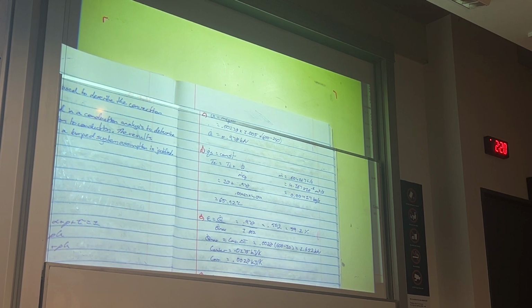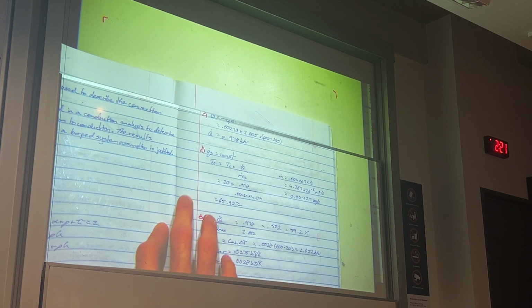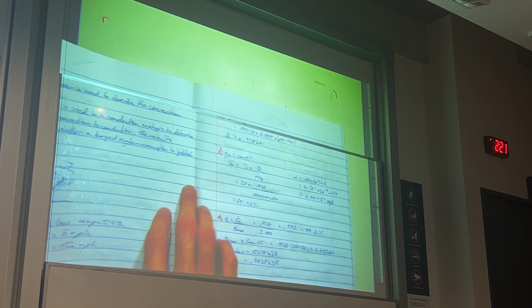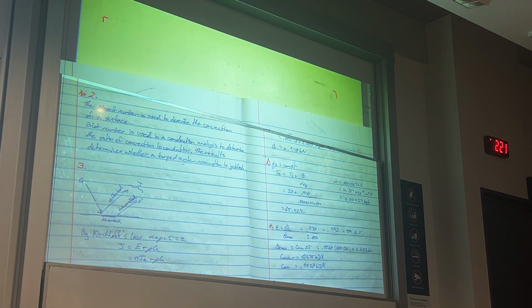And then we want to determine the temperature that our water exits at. So I make the assumption that we have a constant heat flux. So all along our heat exchanger, we're transferring the same amount of heat. I don't specifically remember why, but if you look through your solution, your heat exchanger lectures, there should be something on it.